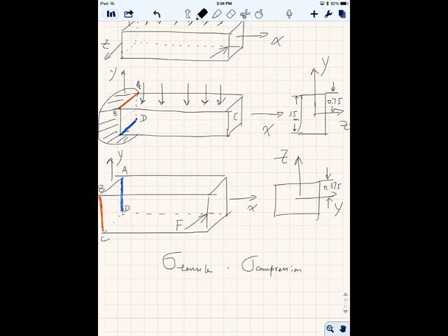Now, on A, B, C, D, two points are very special. What's special about them? They lie on both red lines for the case of the distributed load and the concentrated load. At the same time, there's another point. It lies on both the maximum compressive stress under the distributed load, and also the maximum compressive load under the concentrated load. So these two points are point B and what? Point D, right?